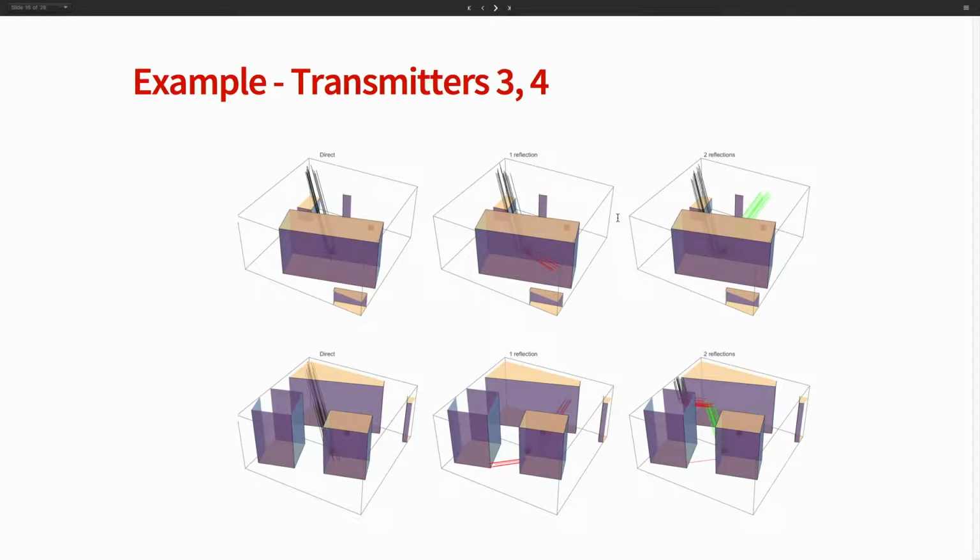Just to see what happens, the red dots are the positions of the transmitters. Usually you have two options. Either you mimic the rays transmitted, but then you have to do lots of rays because you don't know if they actually get their way to the receiver. Or do the opposite, which is usually what is done: you do inverse rays. You transmit the rays from the receiver, because you know where it is, and you collect only the rays that get near the transmitter, which is more efficient. So we can see what happens here in some scenarios.